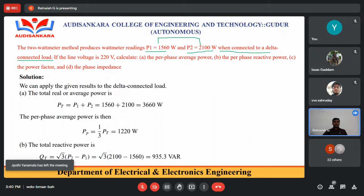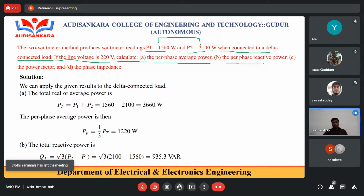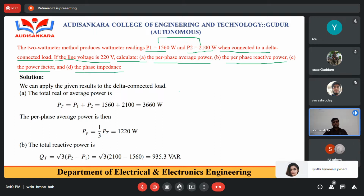Here the load is a delta connected load, and the line voltage is 220 volts, because in a delta connected network the line and phase voltages are the same. So what are the requirements? The parameters we have to calculate are the per phase average power, that is, the average power consumed by the load, the per phase reactive power, that is, the reactive power consumption for the same phase, the power factor, and the per phase impedance. All these parameters we need to calculate, right?